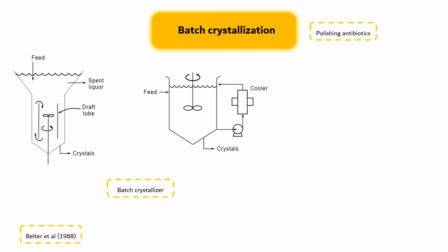These are little more than a stirred tank, which is charged with a warm concentrated solution. The solution is cooled to produce supersaturation. Crystals nucleate, often as the result of seeding, and are allowed to grow until they reach the desired size. Maintaining this growth requires further cooling.